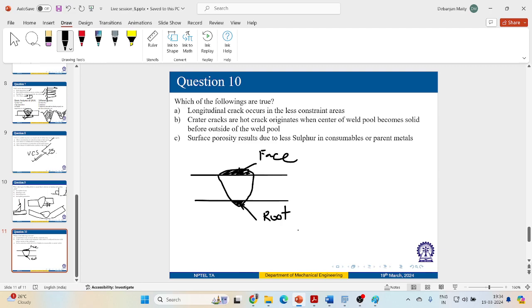There are so many welding defects actually. In between those, I personally feel that cracking is the most happening one. Whenever you do some melting and solidification, cracks will always generate because of those solidification shrinkage, because of those contraction strain, because of the thermal expansion coefficient of that material, right? So, yeah, there is something called insufficient penetration or incomplete penetration.